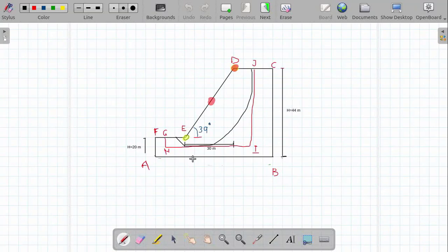And then we will create some points. We will monitor the results at some key points like toe or the top of the slope is an important. These are some two important points where the deformation should be monitored, so that we can identify if failure has taken place or not.